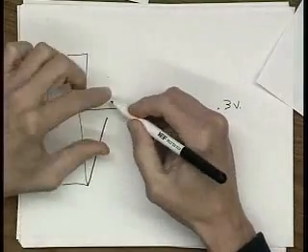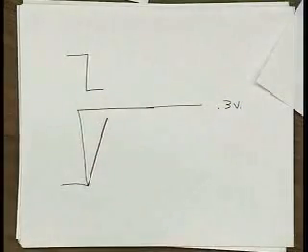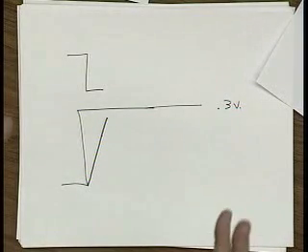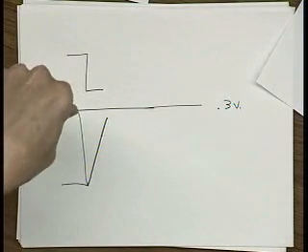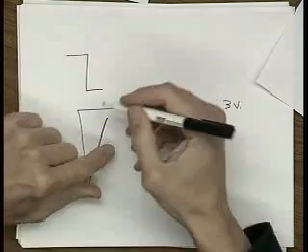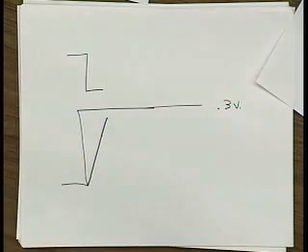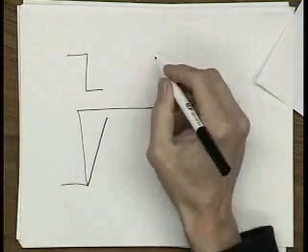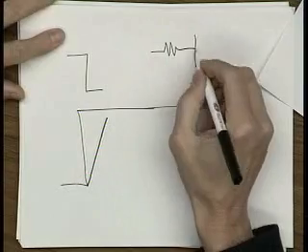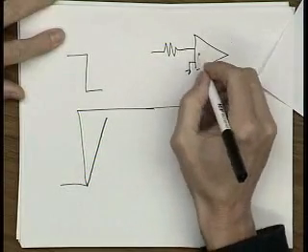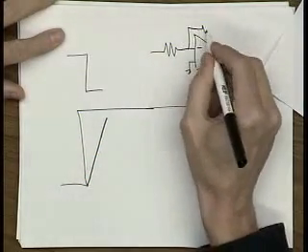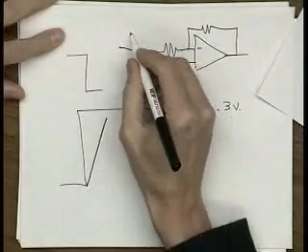After those input pair transistors get back into linear region operation, after one stops cutting off, the input pair is getting within a VD sat or so of its final value. And what's happened here, if you look at this amplifier, is we put a big step here.